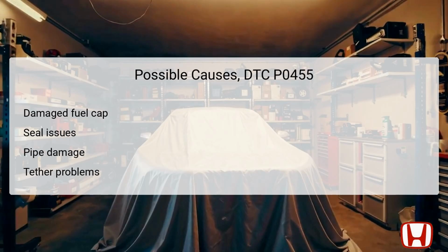Several issues can trigger DTC P0455, starting with a damaged or improperly installed fuel fill cap. A fuel cap that doesn't click into place can easily allow vapors to escape, resulting in system failure. Furthermore, if the cap seal is missing or damaged, it can fail to create a tight seal during operation.